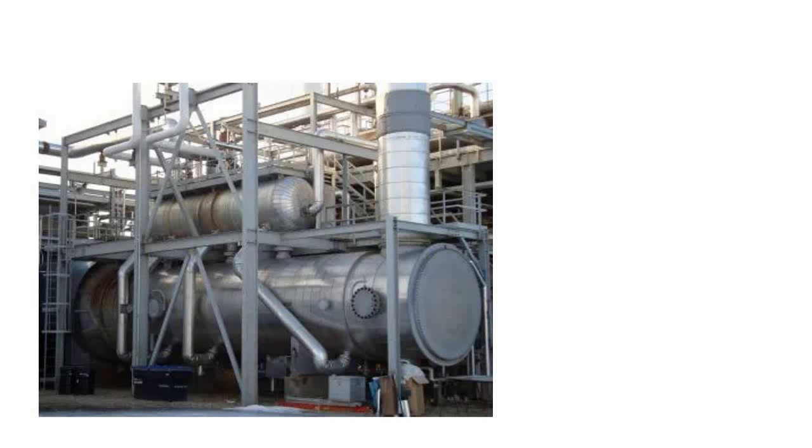Now how do we transfer this vertical force as well as the lateral force? Let's say you have a frame like this, and you have vertical load like this. To make this stable, you can use moment connections in this frame.